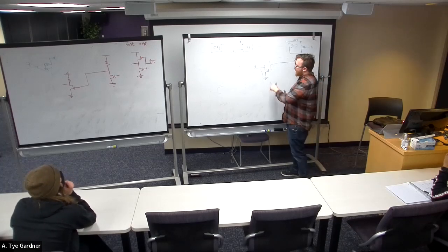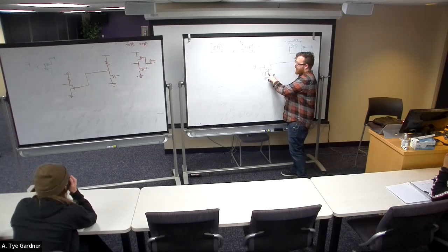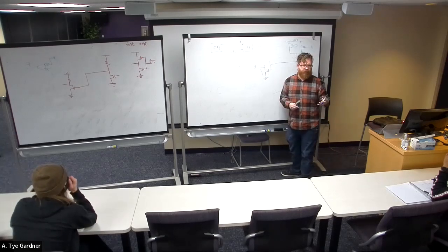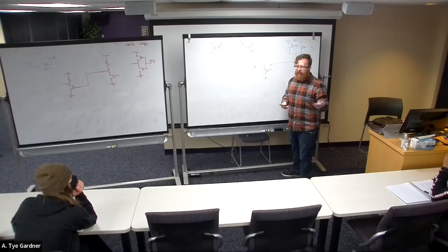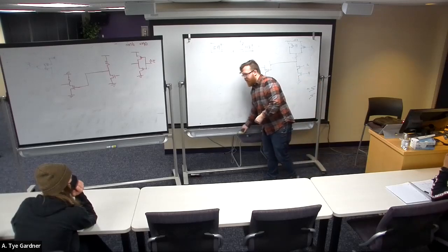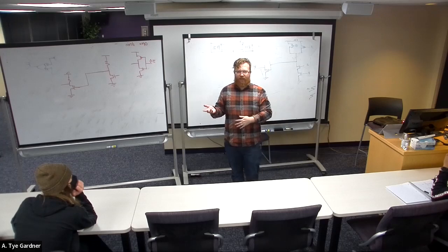And if both devices have this pull down, this open drain circuit, then either one can make a 0, but neither one can make a 1. So they will never find themselves in a situation where one of them is trying to make a 1 and one of them is trying to make a 0. It's that they are either trying to make a 0 or it's a 1. And then all they have to do is talk to each other, right?